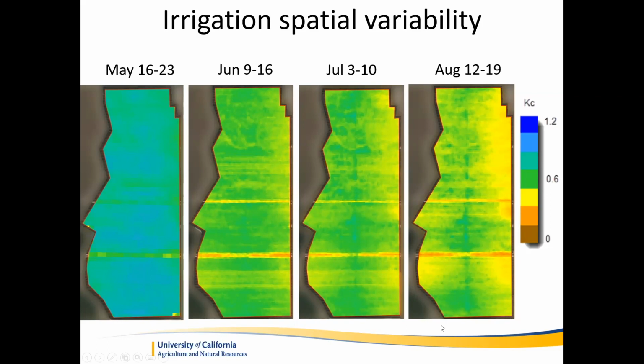And as time goes on, in July, you start seeing more of that pattern. By August, you can see what looks like a vertical area here of higher foliage. That's probably where the irrigation risers are. And then it looks like water is not able to reach the ends of the fields. So this could, for example, indicate that there's a problem delivering water.